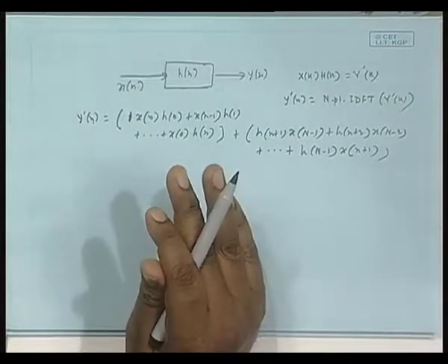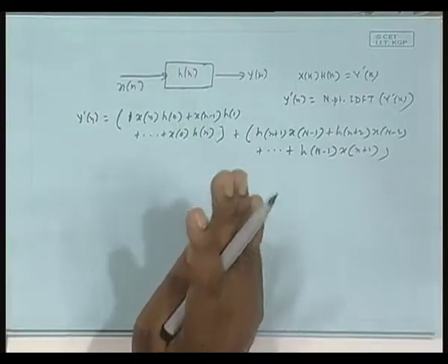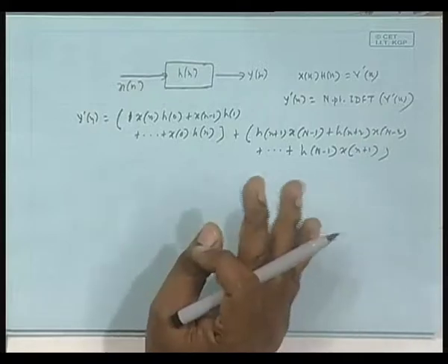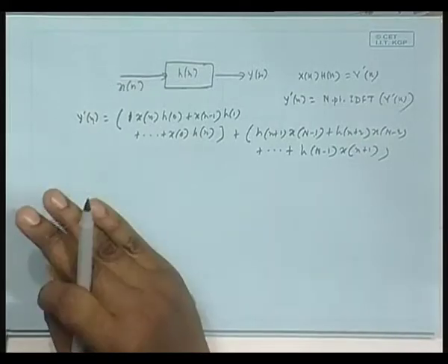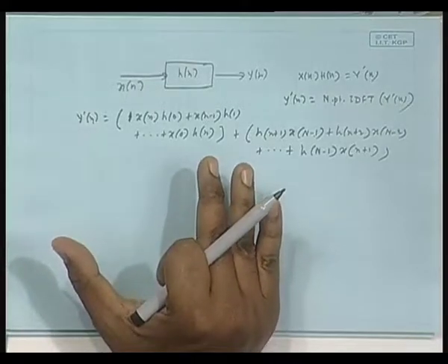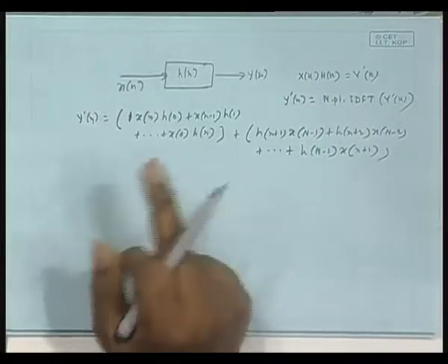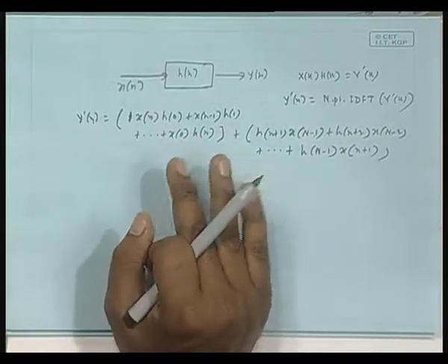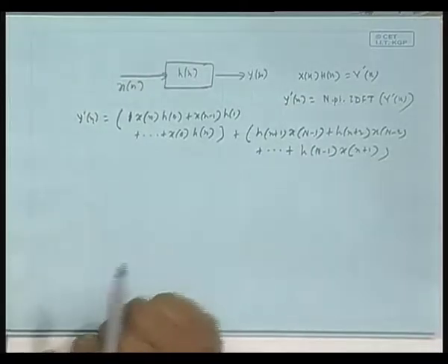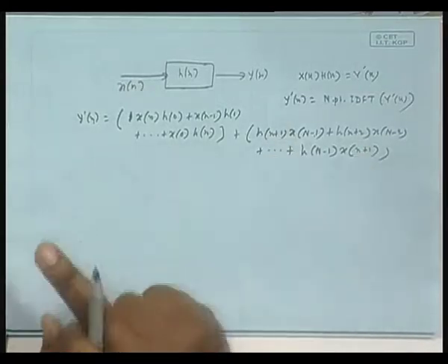After that you still have an infinite length sequence. Now, you throw away the components outside the window from 0 to capital N minus 1, to the right of capital N minus 1 and to the left of 0. So, it again becomes a finite length sequence. So, you have two finite length sequences, h n as it is and one obtained from x n in this manner, and now go on multiplying samples from top and bottom and add them, and you will get the circular convolution. That is my claim, and we will have it verified that it will indeed give you this expression.